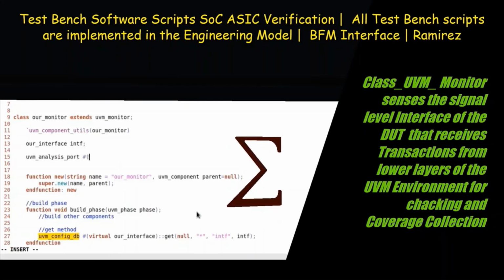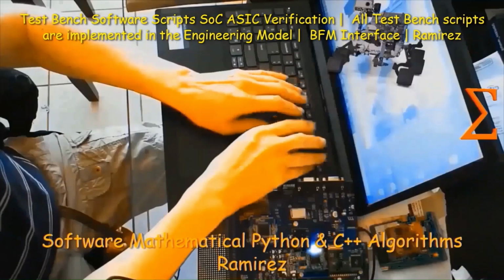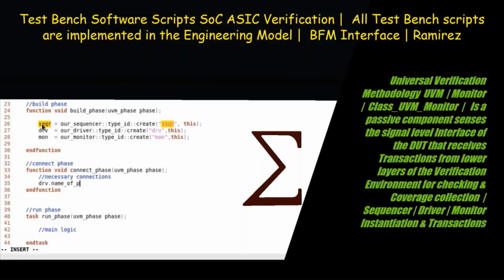So it is important to note, in the untimed test bench, that the virtual interface within the top level configuration object is set to point to the BFM interface within the test harness, that is top_HDL_th.bus_BFM_0.